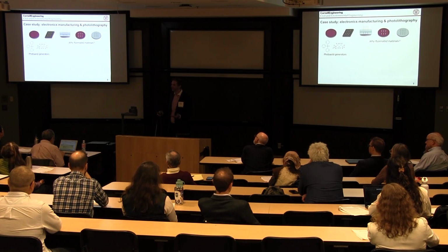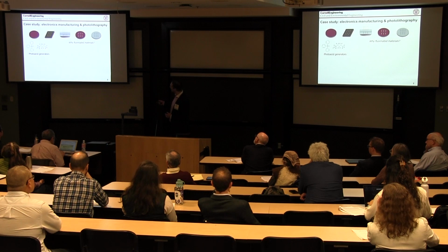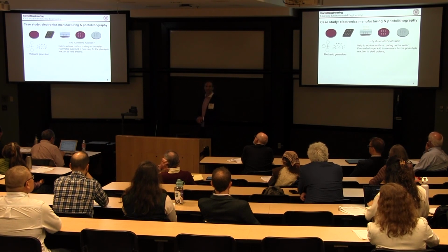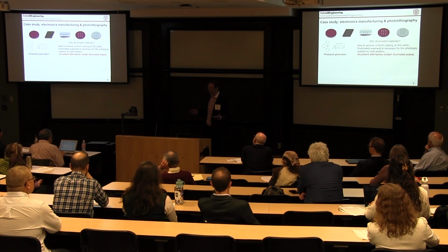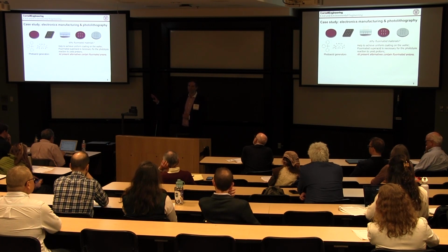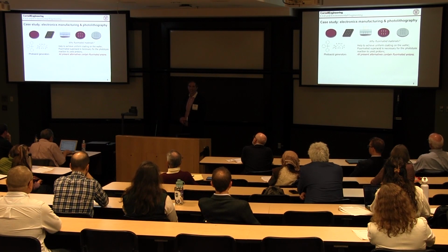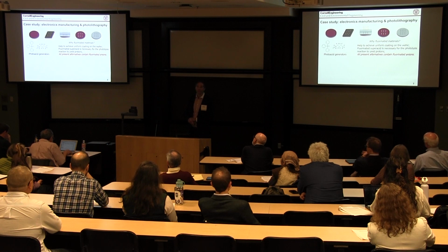They often exist as cation-anion pairs. In photoacid generators used in photolithography, the anion part is almost always fluorinated. In fact, there are no viable alternatives for the anionic component of a photoacid generator that doesn't contain fluorine. So they're almost always a sulfonic acid with some fluorinated chain attached to them.